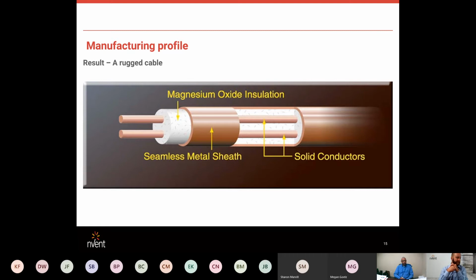That may start out as a Schedule 80 1/2 inch diameter pipe. And those solid conductors, when the product's sent to you, may be something like 18 or 20 gauge conductors, very small in diameter. But they start out, you could say, 12 gauge or 14 gauge. So what we do at the factory is we have, for example, a 1/2 inch diameter Schedule 80 pipe, and then we pack it with, let's say, our 12 gauge conductors and magnesium oxide.